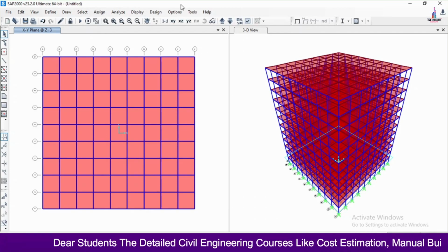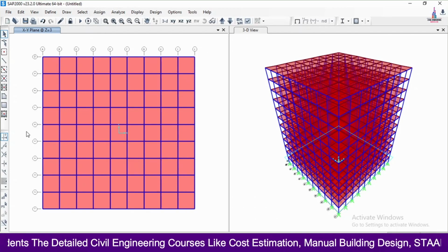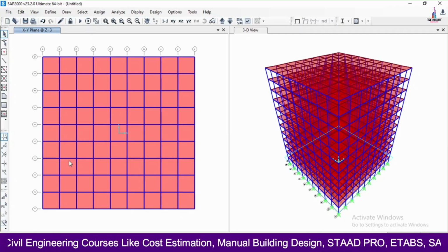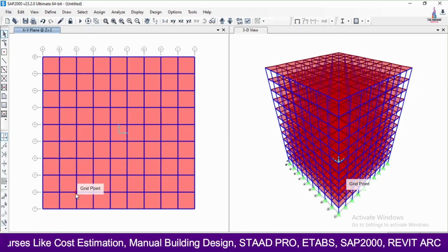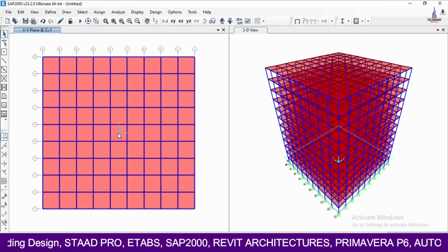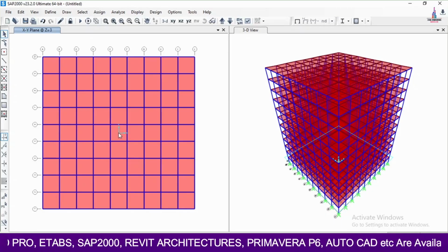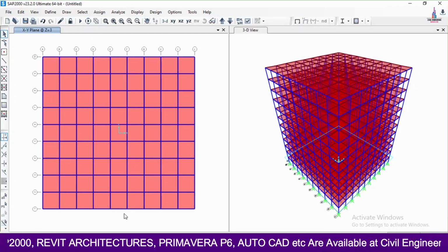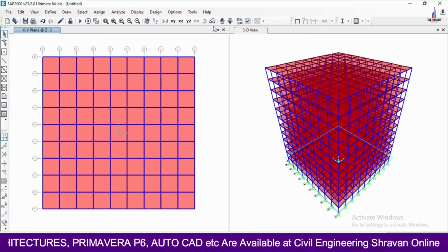So we have to apply the friction damper at this location, which is approximately equal to 3 meter, 6 meter, this is 9 meter, this is 12 meter, 12 plus 1.5 meter, 13.5 meter from the center point of the building, in this direction. So this direction comes under the X direction as well as the Z direction.